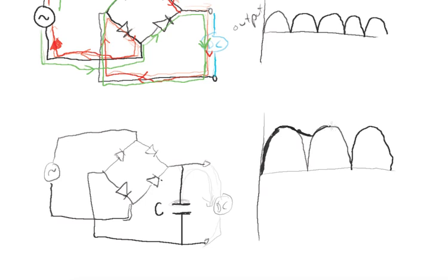And then it goes back up, and then it cuts back down during the capacitor's part while the capacitor keeps the current going. And then it goes back up like this across the top, and then it cuts back down like that. And so what you end up with is a current that's a little bit wavy. I didn't draw that well. It's like an arch, and then it cuts down, and then an arch, and then it cuts down, and then it arches and cuts down. And so you get something like this, but it's a lot more steady than this, right?